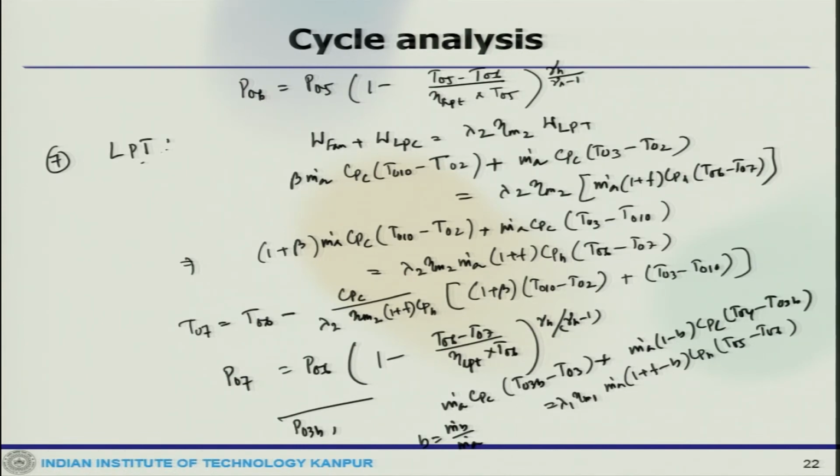core air flow. Moreover, such a bleed has its impact on the energy balance of the low pressure spool, and the air passing through the low pressure turbine is also now reduced.